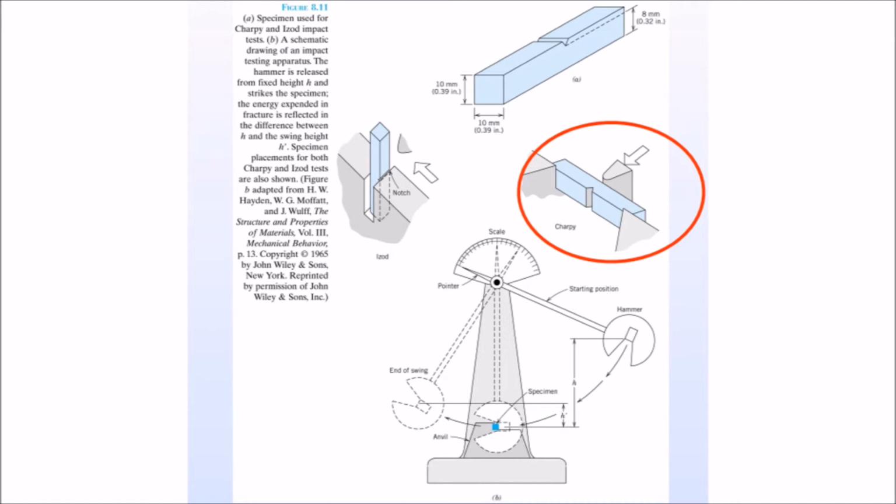The Charpy machine determines the energy it takes to break a sample by swinging a hammer like a pendulum into the sample and breaking it. In order to operate the machine, first the hammer is lifted and clamped in place. Next, a sample is placed in front of a slot in the anvil with the notch facing forward, so the material will break at its center when the hammer strikes it. Finally, the hammer is released so it falls and collides with the sample, breaking it and then continuing along its path through the slot in the anvil.